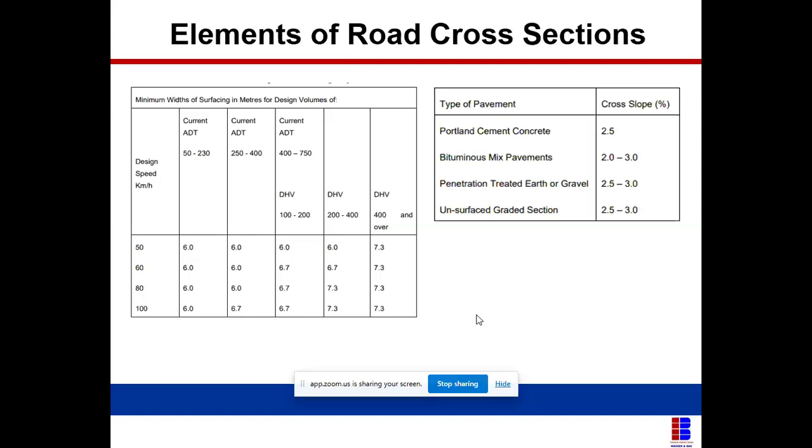All right, thank you. The cut and fill, the minimum should be 0.3% for a paved surface. So what it means is that if I have 0.3% on my road, and it rains, and the water is moving, I'm having a camber of 2.5%. That water will drain faster from the road and go to the drain. But if I'm having a gradient of below 0.3%, let's say 0.02, the movement of the water will be slow. Even with the camber at 2%, the movement of the water along the stretch will be slow, and the water will be going gradually. So the minimum you have to meet is 0.3 for the gradient, then the camber 2.5. So the water will move faster and go out of the road faster.